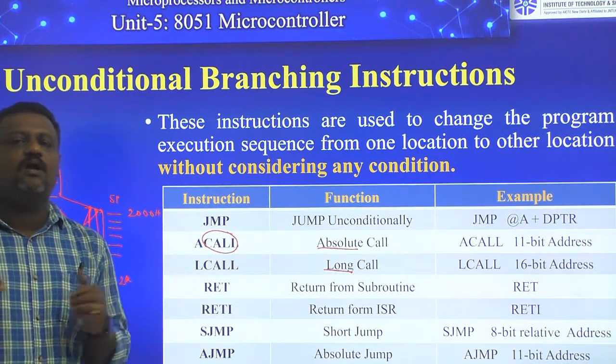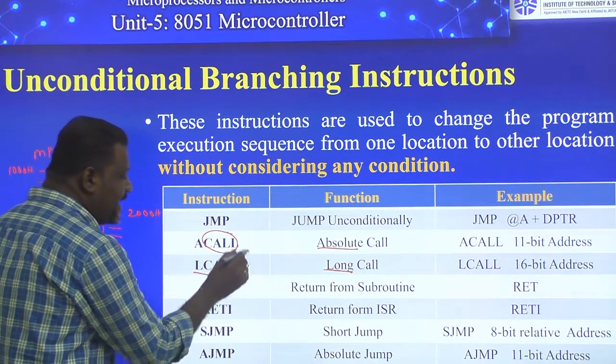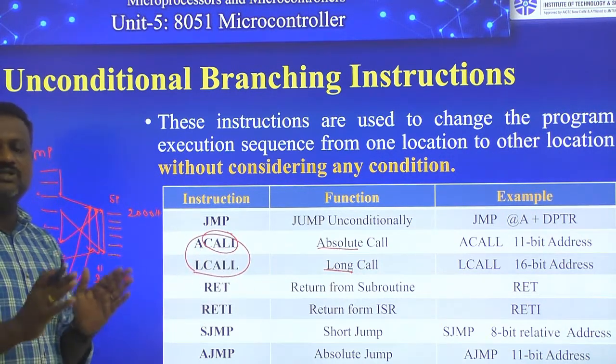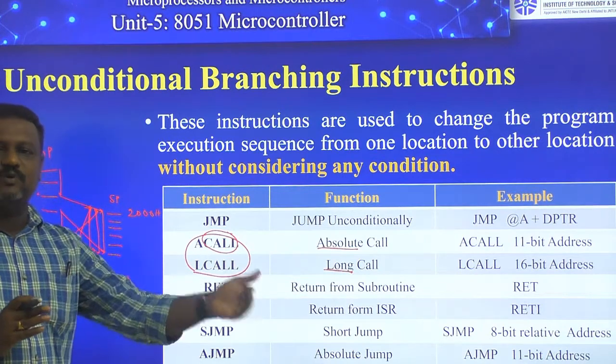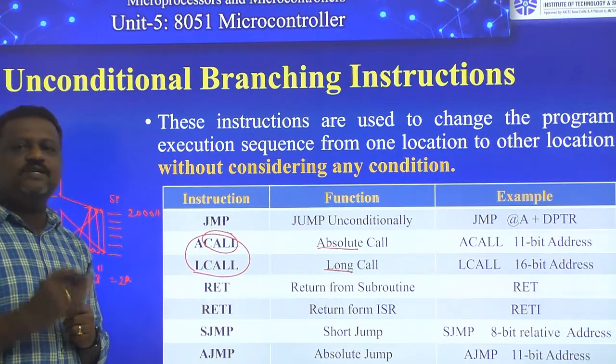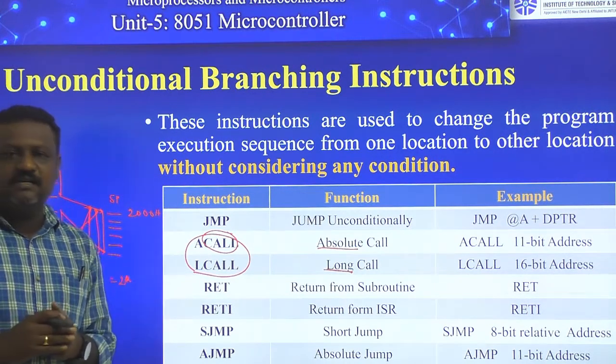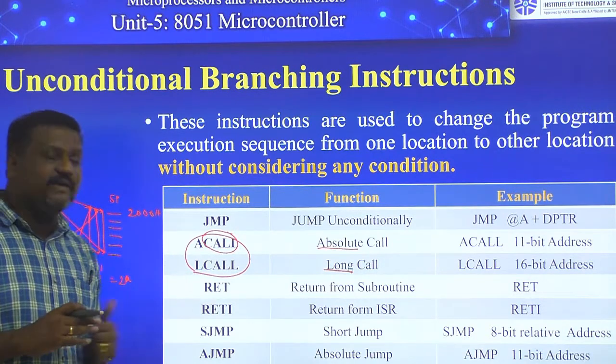L call means long call. So finally what I conclude is this: ACALL and LCALL, both instructions are used to call a subprogram into the main program. So that is about this. And one more instruction we use when we are communicating with subprograms is RET.